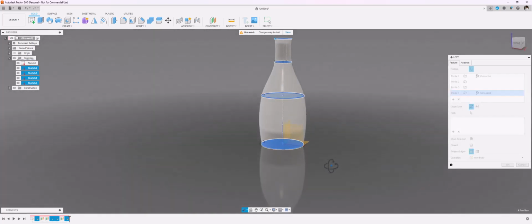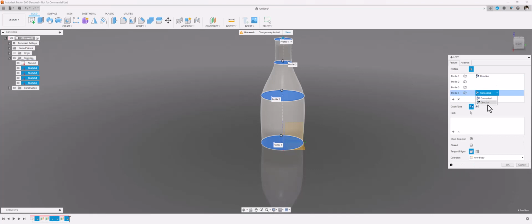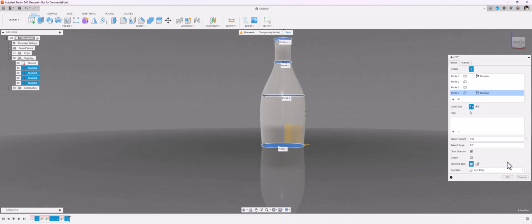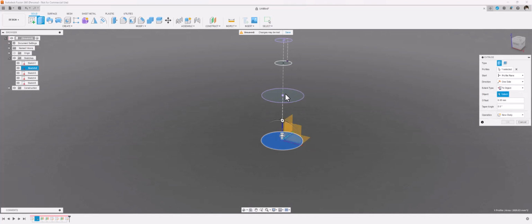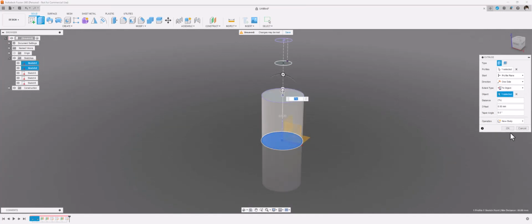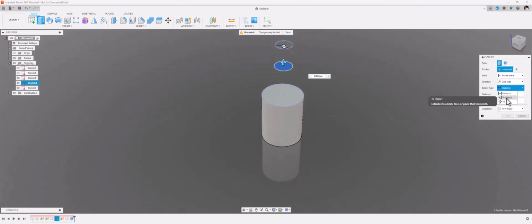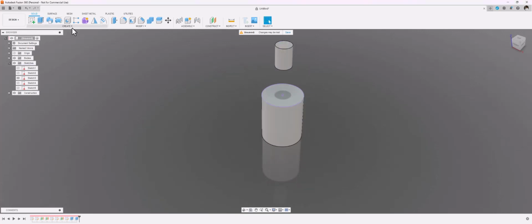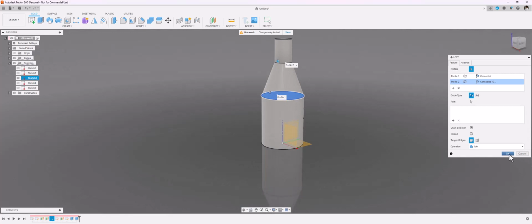And you see we've got more of a vase shape. We can tell it that is the direction it wants to go, and it will behave slightly differently. We can tell it that this profile is also the direction, and we get another shape. It's rounding it a bit more. If that's not what we want, then we just simply go with saying this to here, and extrude this one to here. It's important to select the to object, otherwise it remembers the actual distance. And then we'll use Loft, and for a single step it should give us a nice simple line like that.